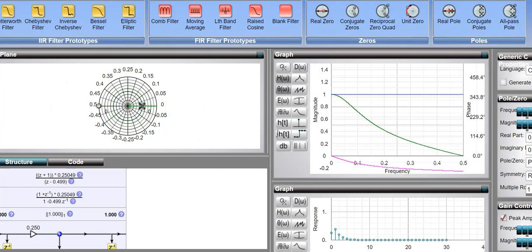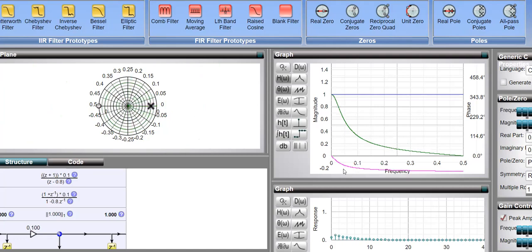So whenever we put the poles closer to the unit circle, you can see that your phase response is more non-linear in properties, but the quality of the filter improves. So you need to make a trade-off between non-linear phase and the quality of the filter. Okay.